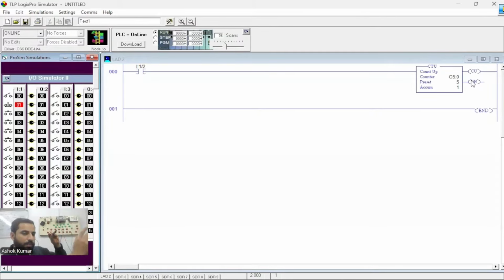But when the object moves, the sensor value becomes 0. So now it is not giving any logic to the counter, right? Again, a new object comes into the scenario. Now the sensor again senses the object, again giving the logic to the counter, which makes the counter value 2. Again, the object moves and the sensor becomes 0. That means for a counter, we need an input which is on off, on off, on off. We need all the on and off pulses to run the count. Most of the time, when we count products, we have a sensor which gives 1-0 logic, right?